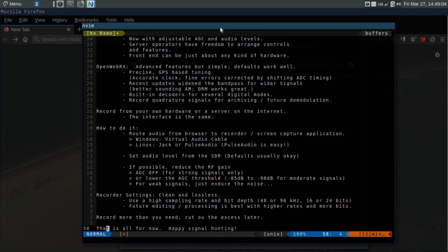No good. I'll tell you what, when I upgraded to captain, the first thing I did on my oceanic trips was teach my co-pilots how to reduce the gain to a more reasonable level. Not so low that you miss SELCAL calls, that you miss calls from ATC, but reduce the level a little bit to reduce the listener fatigue. And it's funny.